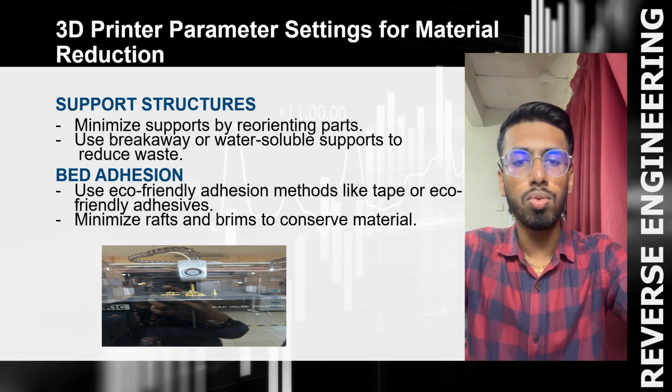Breakaway supports are used in this project. They are easier to remove manually. It's a simple post-processing. This reduces waste and makes the finish process cleaner, especially useful when complex geometries are involved in the door latch design.